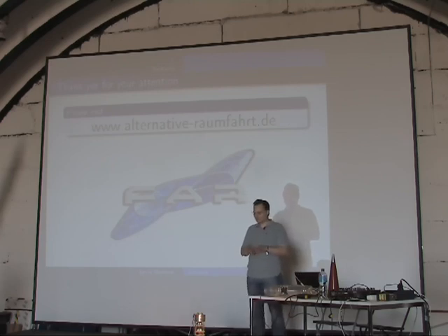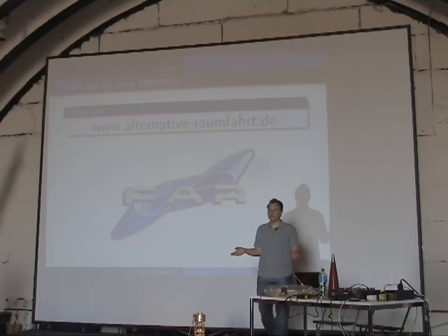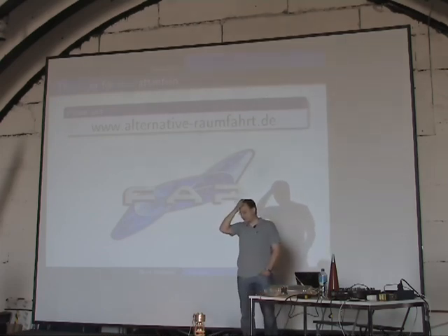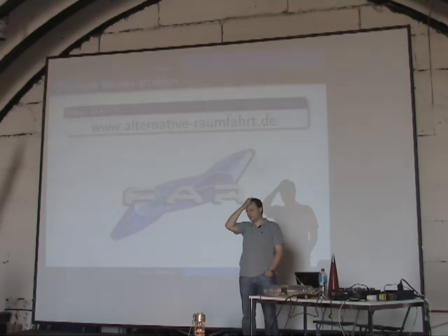But if you have totally redundant subsystems, so 2 subsystems that could control the attitude, then if one subsystem goes wrong, the other has to correct for it. Yeah, this is very difficult, because if one thruster opens one valve totally, the other cannot overpower it. And so you're in a stalemate, and you lose control. So this is a really difficult problem. There's no exact solution to it at the moment, although I don't know of any.